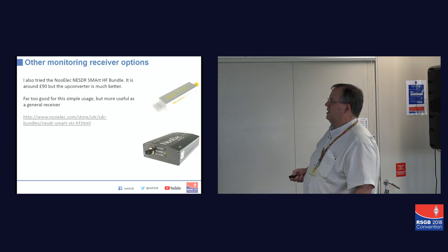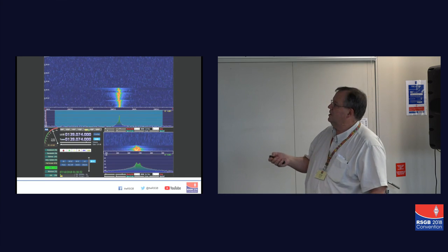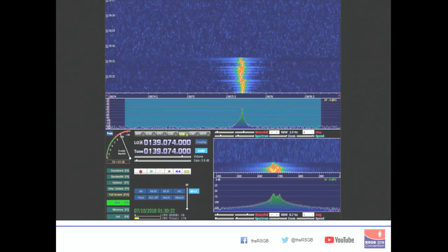Sounds pretty much like an FT8 signal. And as you can see, it shows us the splats on startup quite nicely and the intertone splats. This is a bit closer in, and as a result, you can see the sidebands that it creates. So, you know, they're not just mathematical, they are real, and that's the overall shape of the signal. That is between, I think, 1400 and 2000 hertz. That's about 600 hertz wide.